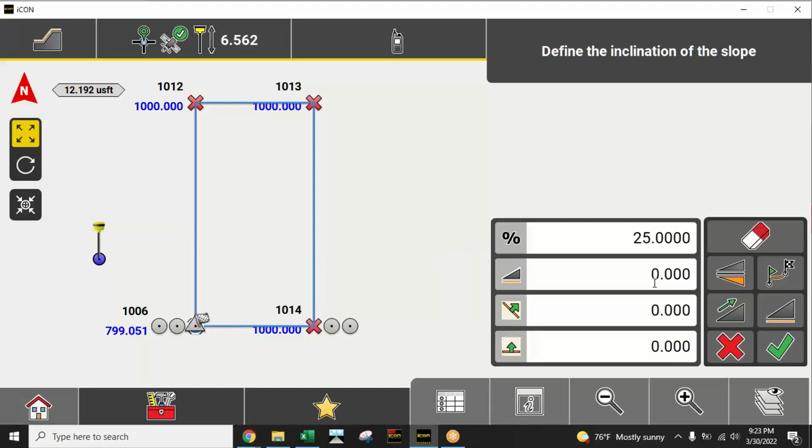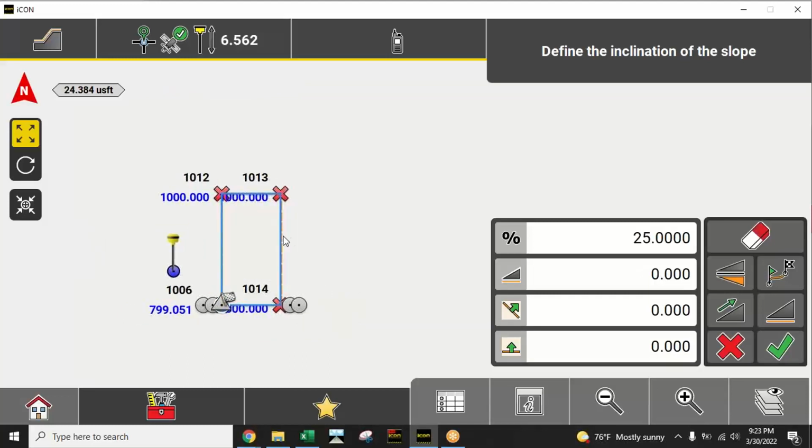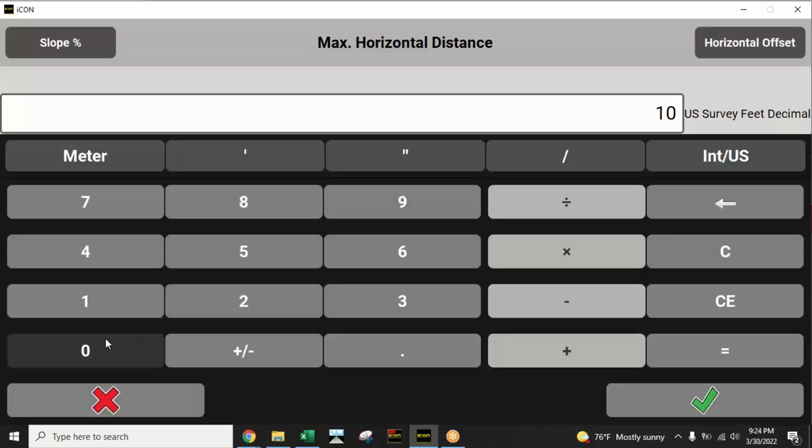I would just make sure that if I was doing this on the fly and I was sloping this away from this pad and it's going to basically hit grade out here somewhere at a variable distance, I would make sure this number goes out further than my tie-in point. That way you got a true clean model all the way till you hit your catch point on your existing grade around the perimeter here. So we'll do that, 100 feet.